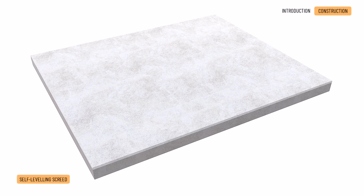The surface of a finished subfloor may not always be perfectly even. In such cases, a self-leveling compound can be used to create a completely flat and uniform screed suitable for covering. The flowing, fine-grained self-leveling layer typically has a thickness of 2 to 10 millimeters, up to a maximum of 20 millimeters. First, a primer must be applied with a roller.